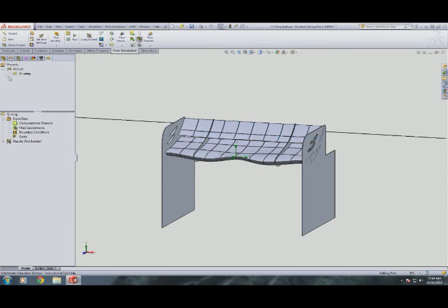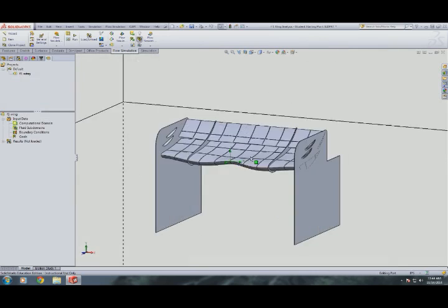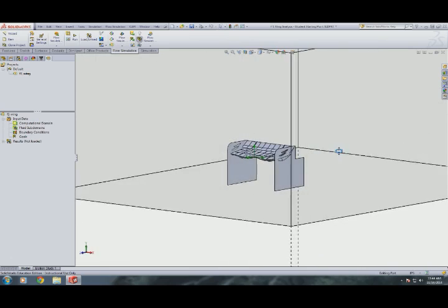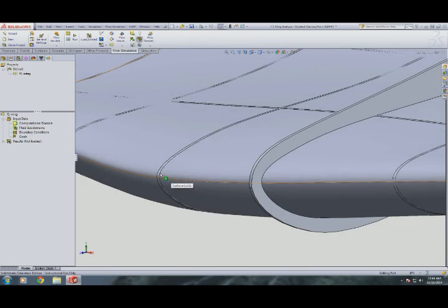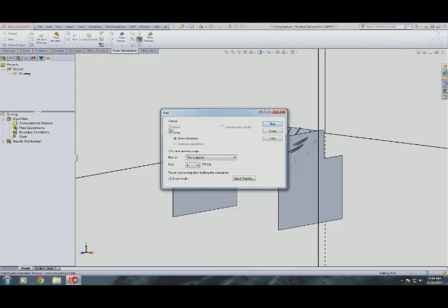I've actually not tried to run it with that still turned on, but everything else I've done in SolidWorks tells me that when you have two solid bodies interfering with each other and you try to run analysis on it, things just aren't going to work great. The fact that both of the surfaces exist on the outer mold line of this model would probably throw CFD for a loop. Okay, let's run it now and see if it works. Meshing, solving, new calculation. Yep, let's go.